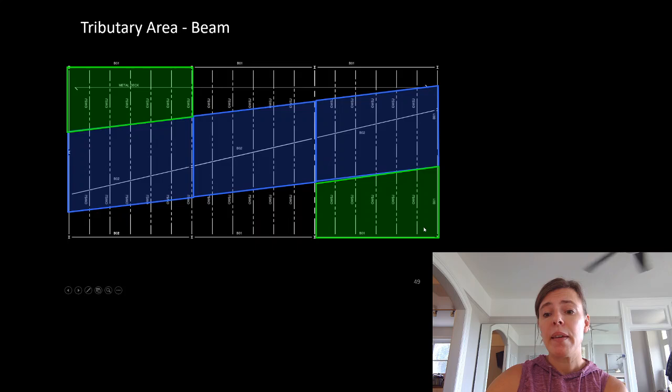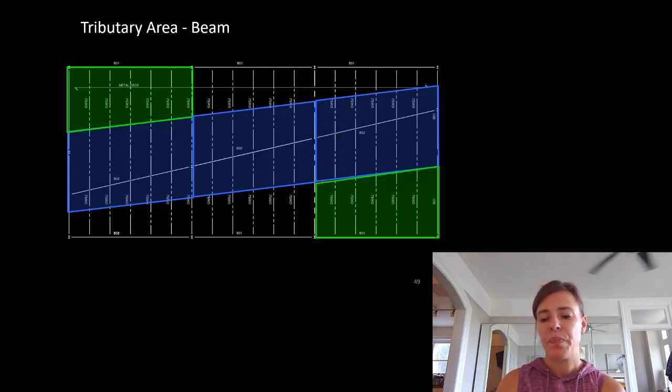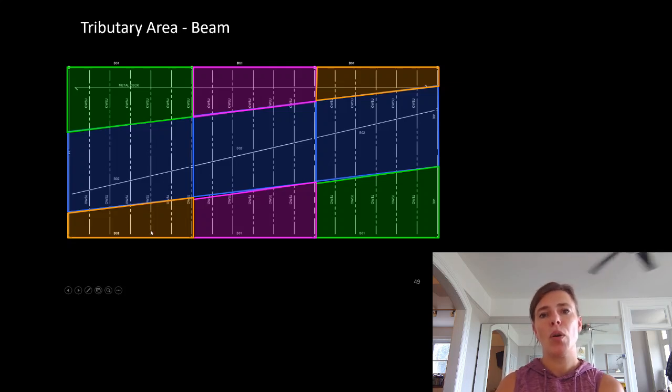And these two beams, same length, same load distribution. Assuming they had the same load on them, we could design them as the same beam. These should probably have different names, but these two beams are going to be the same, and these two beams are going to be the same. We might say, all right, that's a lot of work. All three of these beams are kind of similar, so we're going to design for the worst case. Acknowledging that all three of these have different load cases, we might only design one of them and apply it to all of them. We have to be very diligent in how we track those things. I would expect you guys to keep track of them as three different beams.